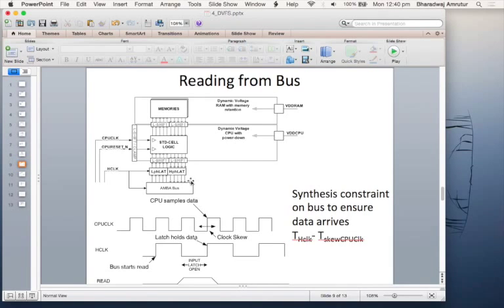So what you have here is a situation where you have this block which is in a separate dynamic voltage domain, and then you have the rest of the SOC. For example, maybe this is connected to the bus. The name of the bus is AMBA bus. It's just one of the standards used which allow you to hook up multiple peripherals, multiple devices onto this bus. So how do we transfer information across and make sure timing is not violated, right? So this is an approach